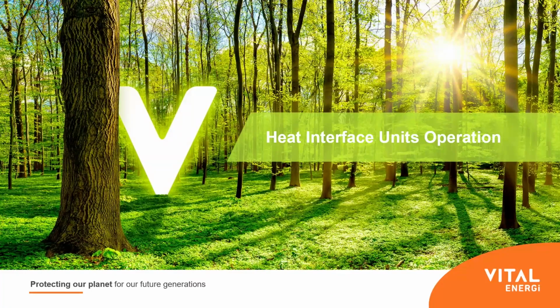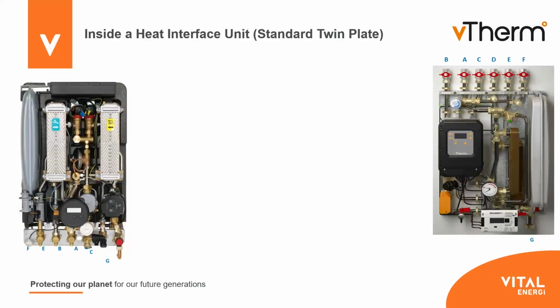So let's talk about the operation of HIUs. If we start looking at the components within a HIU, on the left-hand side, you can see one manufacturer, on the right-hand side, another manufacturer. And one of the things that you'll see, main difference is one has top entry pipework and one has bottom entry. Both don't matter because normally you'll have some form of bracketry that you can pipe up. You can stand HIUs off the wall with a bracket and therefore bring pipework downwards or take pipework upwards. There's all different flexibilities, so it really doesn't matter, especially with new builds, what you're doing.